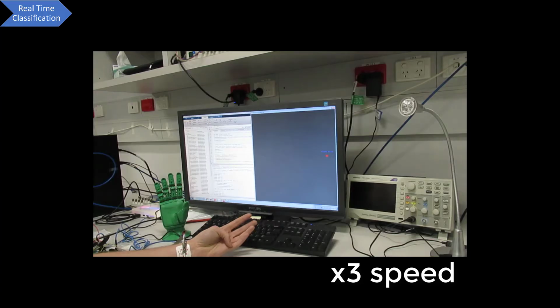Choosing the time domain features, including the autoregressive features, a classifier was used for real-time processing of the signal. This resulted in an accuracy of 78% for the 7 hand positions. The classifier had difficulty in distinguishing between the middle and small fingers.